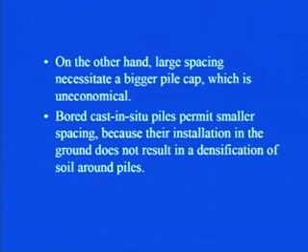Bored cast in situ piles permit smaller spacing because their installation in the ground does not result in the densification of soil around the piles. So, you see how important spacing has become as far as group action of the piles is concerned. The aspects of deciding the spacing of the piles depend on the type of soil, the type of pile that you are going to install, and the method of installation of that particular pile. All these aspects we will be studying in detail in the subsequent class.